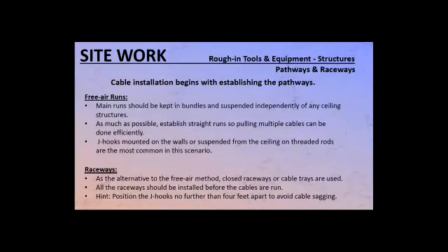They would have those hooks on a stick, those grabbers, and they're going to try to bring some of the ceiling down. If there are other things tied to that ceiling, it's going to be that much more dangerous for them, and they're in danger being there already. So that's why all the cabling has to be suspended independently in the ceiling, and something called J hooks are a very popular thing. We'll cover that further along.